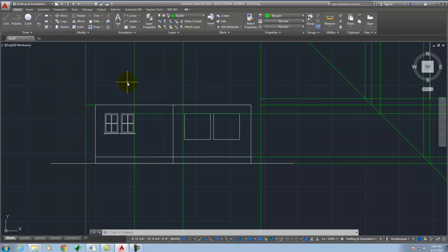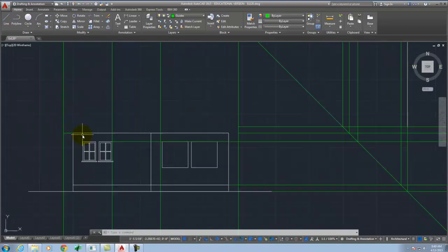It's a very benign slope, but that's about the minimum you'd be going if you were doing asphalt shingles. You could technically go to a 2 and 12, but they don't recommend it on a lot of the product packaging. Anyway, knowing that piece of information, if I wanted a 12 and 12, it's easy. It's 45. If I wanted a 6 and 12, I can do it in two ways.